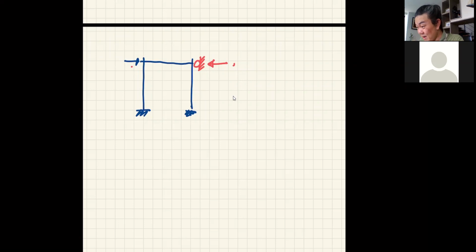Let's say I remove this first. You know that this frame is going to sway, correct? Yes, of course, it is going to sway, and therefore it is going to deform. There will be moment, even though there is no load on the member. Now, if I apply the restraint and stop this frame from moving by adding the lateral restraint there, because there is no load on the member, your structure will have no moment at all, correct? Because this restraint takes care of everything. This reaction will have to be equal to that force, and so the frame will remain intact. No deformation, nothing.